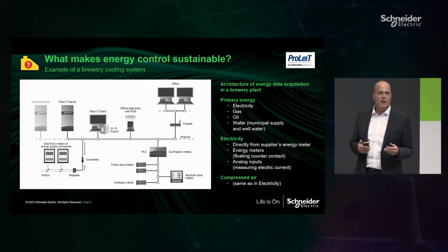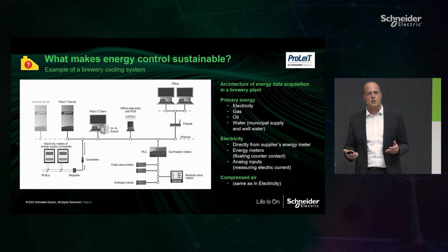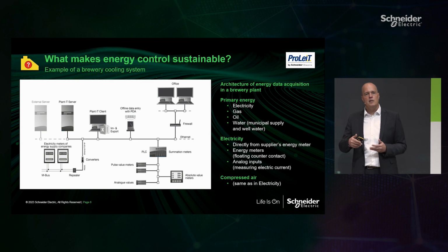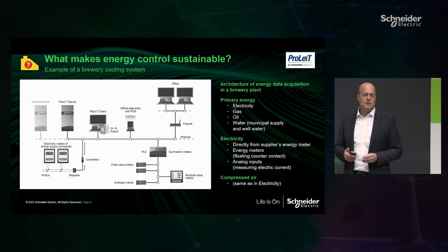We have many use cases where we find out only by monitoring, okay, why is a compressor starting on the weekend when there's no production? Maybe there's a leakage, yeah? And with that kind of information, we can drill down and we can see, okay, how we can avoid it. And therefore, our end customer saves a lot of money because they don't need to run the compressors over the weekend when there's no production, and it makes it easier to find this energy consumption.